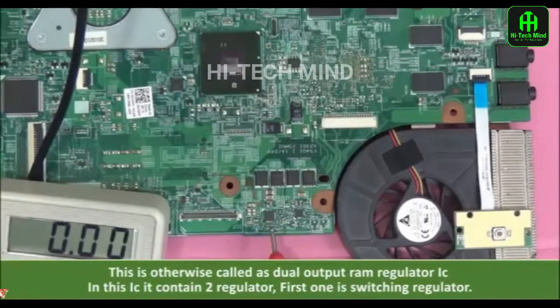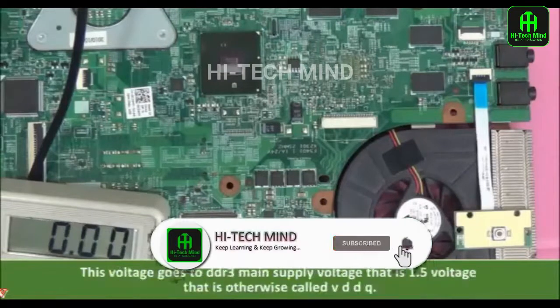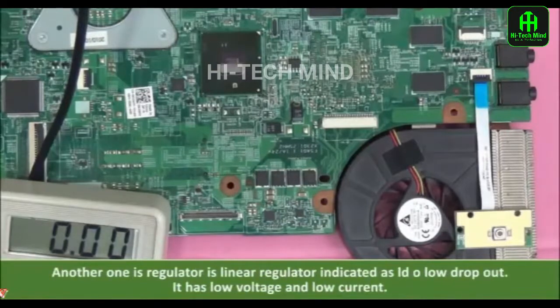This IC contains two regulators. The first one is a switching regulator. This voltage goes to the DDR3 main supply voltage, that is 1.5 volt, otherwise called VDDQ. And the other one is a linear regulator, indicated as LDO, low dropout. It has low voltage and low current.